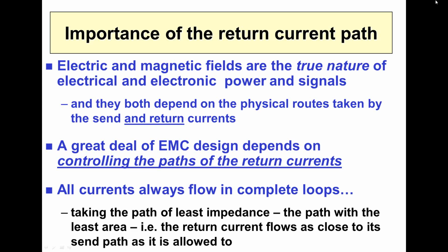You may remember in the previous webinar on November 27th, I said that we often complain that the emissions from our products are malign in some way, that they're trying to work against us. In fact, whatever arrangement of conductors you create with PCBs and cables and metalwork and what have you, you always get the smallest field pattern with the least emissions that that design is capable of, because that's how the laws of nature work. They're always trying to minimize field energy. So you only have yourself to blame, or we only have ourselves to blame, if we've got emissions that are too high.